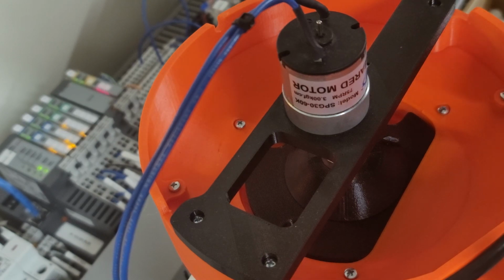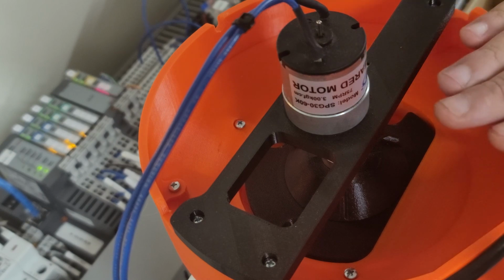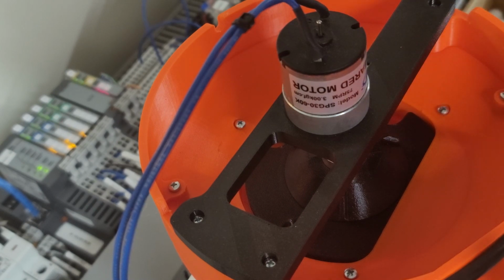Now, again, that illustrates the thing I was talking about earlier. When our voltage dropped below that 2 volts, the motor stopped because the drive stopped sending anything out. But the relay didn't click off because in the program, our speed had not reached that 0.2 volt value, or the 0.2 RPM. But that just demonstrates the ramp up and ramp down of the project.